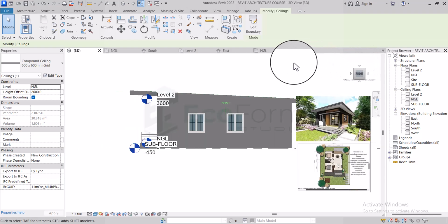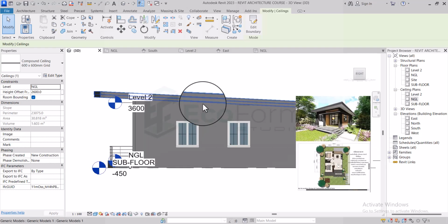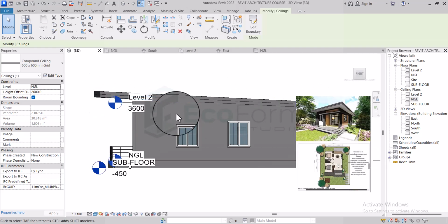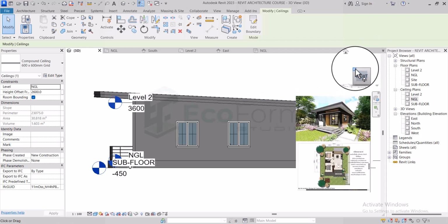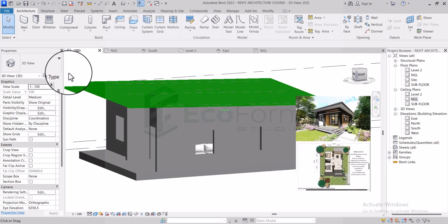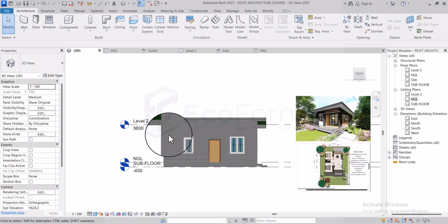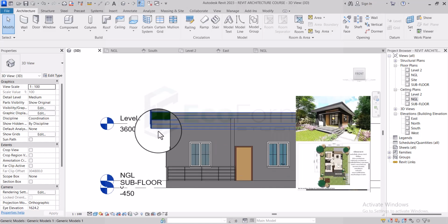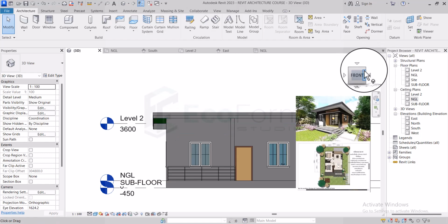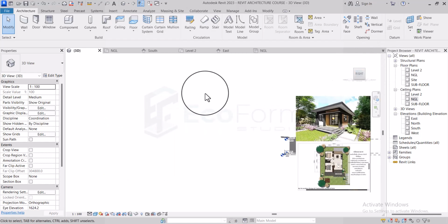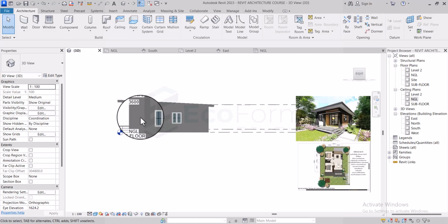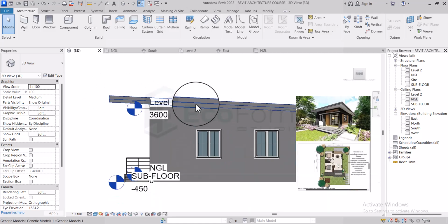You want to do a sloping ceiling, so it is better to use an elevation where the slope can be felt more. If I use the front elevation, the slope would not even show, it will just come as a straight line. So I won't even be able to do it, it would just be straight, just like the one I finished in the interior. But when I select an elevation where the slope can be felt, that's how I can create the ceiling.